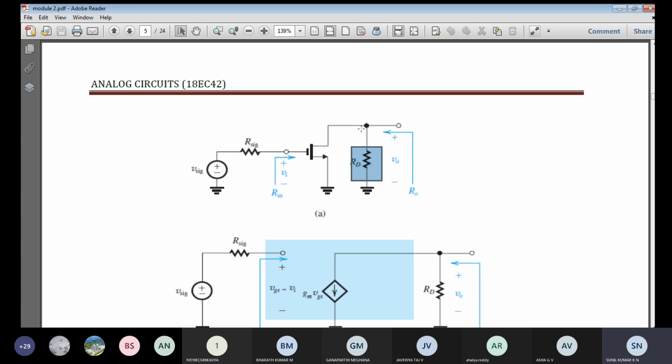In the next chapters, when we discuss feedback or the negative feedback chapter, we are going to see that case, where some resistance connects the output to the input. But here, in this discrete circuit common source amplifier, there is no effect between output and input. There is no loading effect seen from input to output or output to input. Hence, this type of amplifier is called a unilateral amplifier.